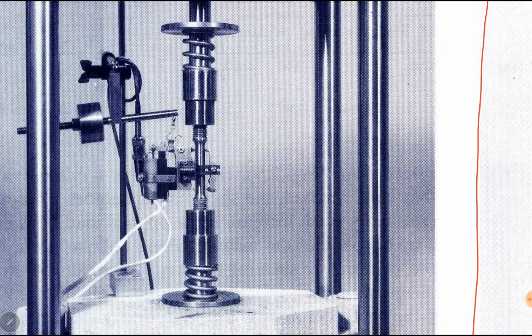Similarly for CD it is given as 600 millimeter square. There are holes here. First we have to find forces, because we know cross-sectional area, we know length of the two bars, we know E for the two bars. So if we know all of these things and we have to find delta, we just need force.